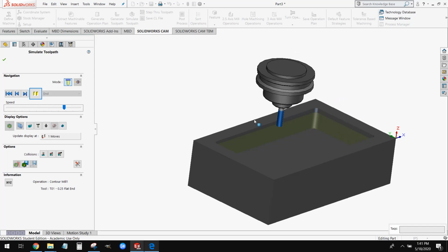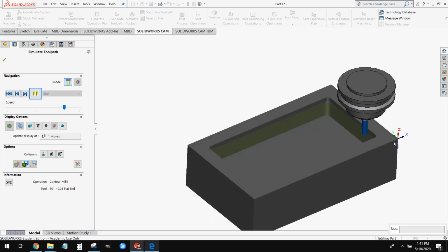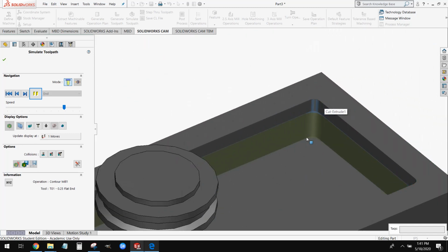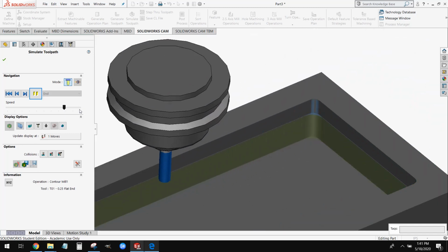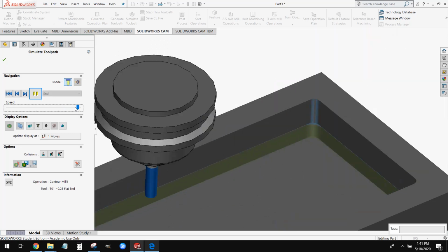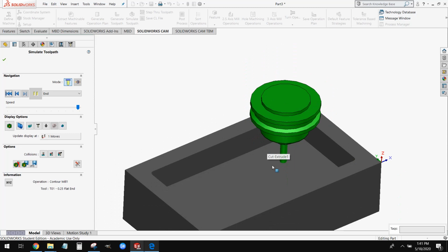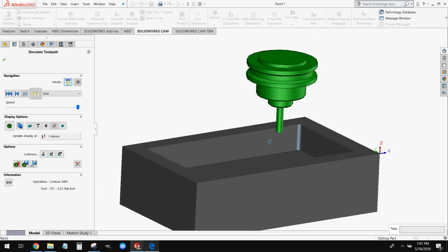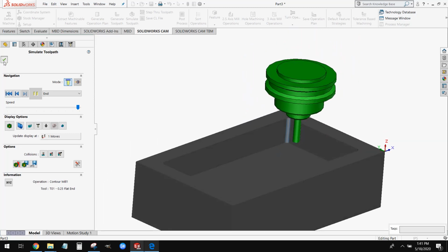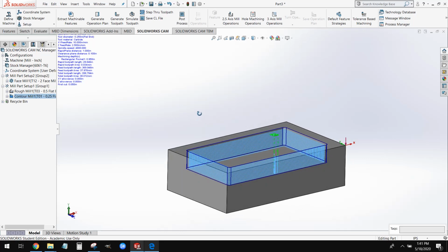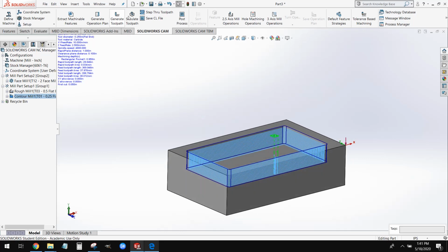And then it should come in here with our 1/4 inch end mill. And come in and clean out the sides and clean off these corners. And that's all looking pretty good. So let's let this continue. And that's perfect. All right, great. So our tool path for this is done. What we would do is post-process this like we did last week. And if you guys can go ahead and save this model.